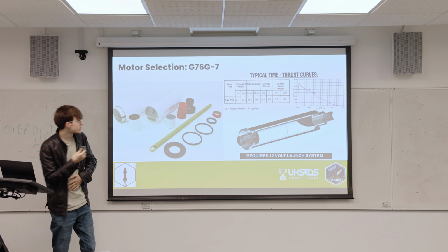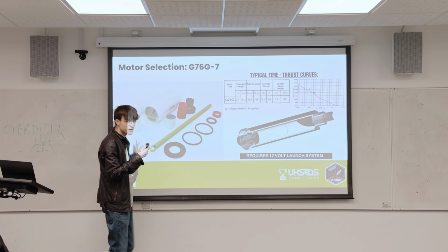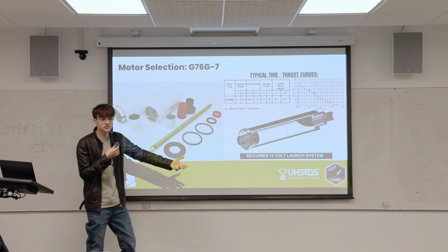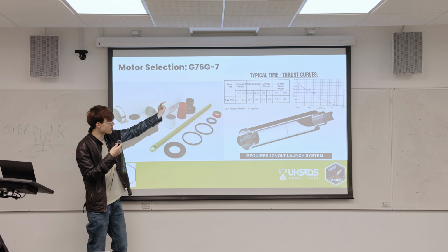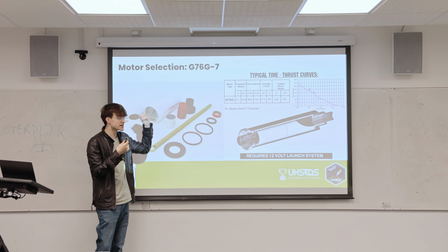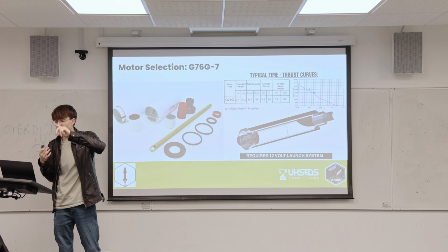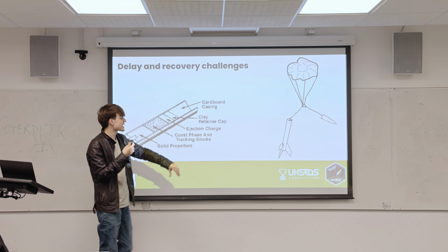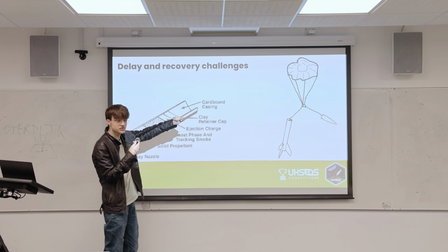So, the way the motor works is we have burning solid fuel. Once it reaches its total burn, which is about 2 seconds, it will start a preliminary charge. The fuse will then light up, and once it reaches the end, a charge will burst. That charge will separate the rocket. So when that charge bursts, that change in pressure will force the rocket apart.